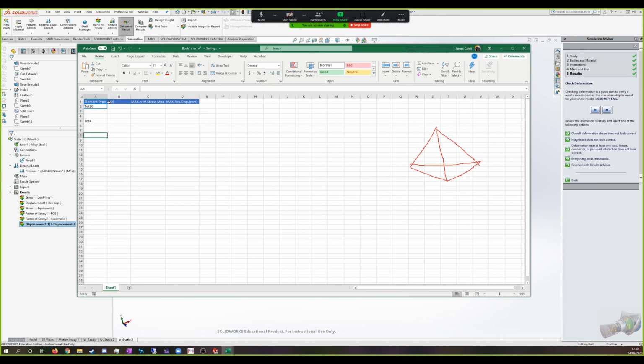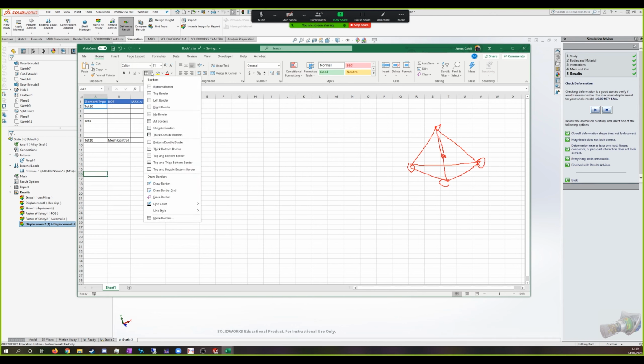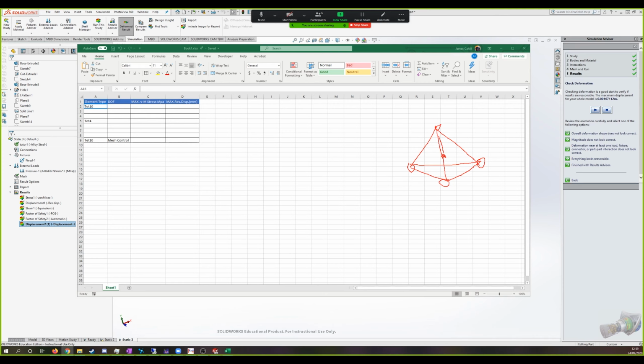So that's what a Tet looks like, right? Tet 4 has 1, 2, 3, 4 points. Make sense? The stress is calculated at the center of the Tet, and then interpolated to each of the vertices. The vertices are shared between each of the tets that surround that vertex, and then averaged. Make sense? Okay. Gotcha.